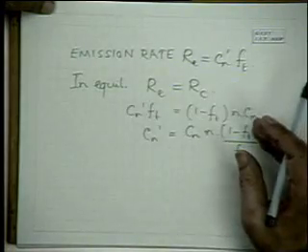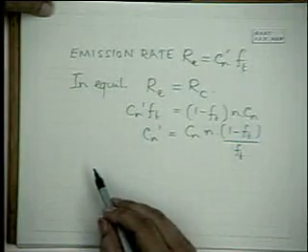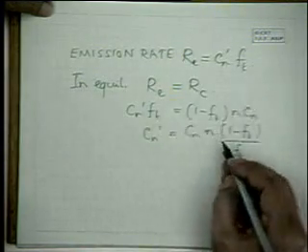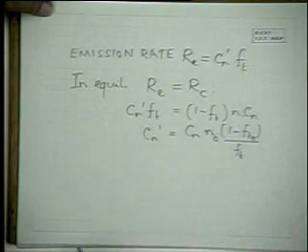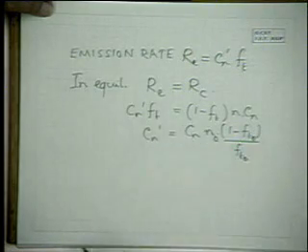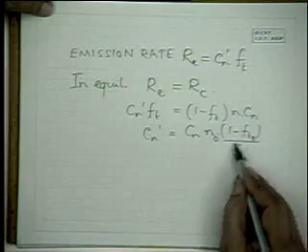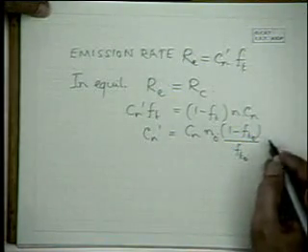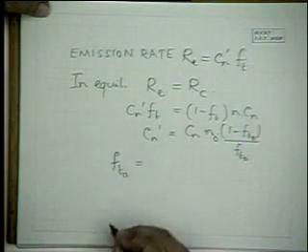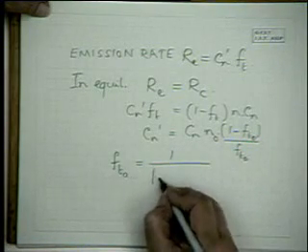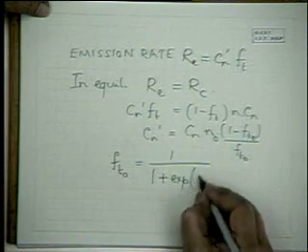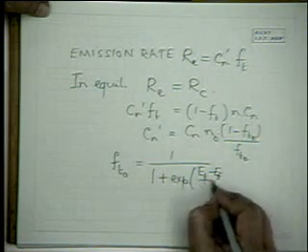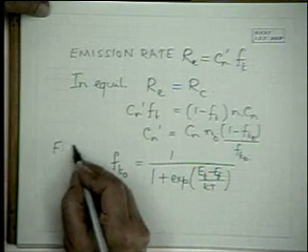What we mean by equilibrium is when there is no additional source like light or bias, which is creating extra carriers, which is adding to n and p. Now, if we talk about equilibrium values, then we can say that without any additional stimulation, n is equal to n0, and the distribution functions are Ft0, 1 minus Ft0, probability, this state is empty, and this is the probability that state is full. So what is Ft0? These are for electrons, so this is nothing other than the occupation probability given by the Fermi function, as given by FD statistics.